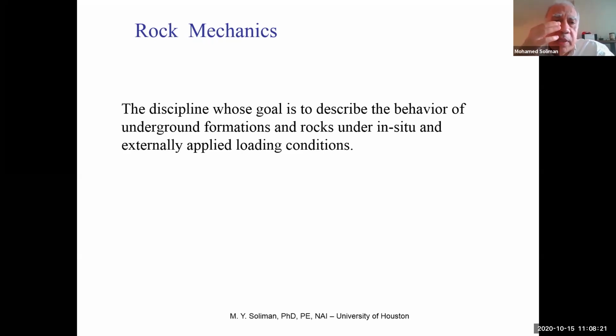So let us talk a little bit about rock mechanics, because that's what we need to understand just before we get into the stresses. So what is rock mechanics? Basically, it is a discipline that you use to describe the behavior of underground formation and rock under in situ stresses, or sometimes externally applied loading conditions. That's what you do in hydraulic fracturing. And when you couple the fluid and the rock mechanics together, that's when you talk about geomechanics. And we'll be talking about both in the rest of the hour.